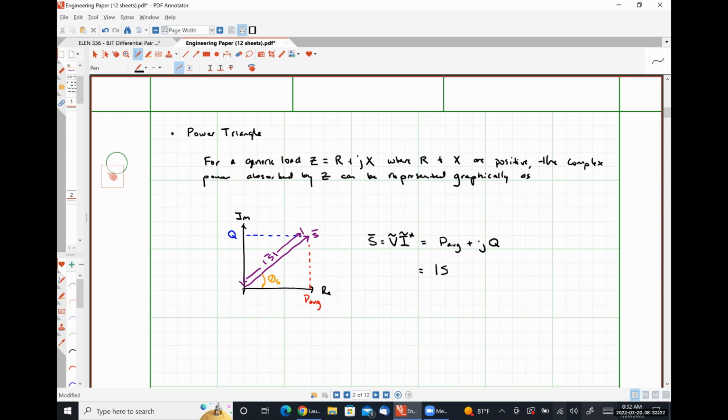And then in our polar form representation, we have apparent power angle power factor angle, okay? All of this information is buried inside this power triangle. And it's interesting here that all of this information is actually just buried inside of your calculator's ability to convert back and forth between polar form and rectangular forms for complex numbers.